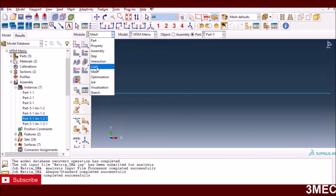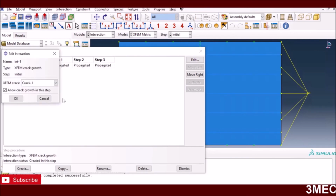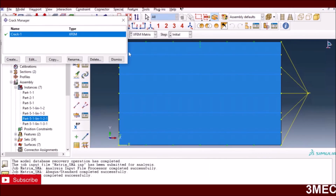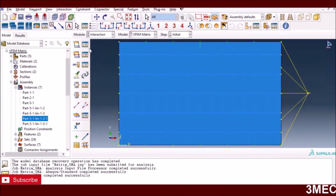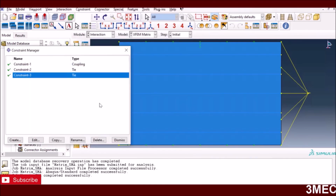All right, and yeah, interaction I didn't show you. So interaction I missed, for example. In this case I have an interaction which is the crack. If you go back to part 1, I showed you how to define this crack. You have to go to special, if you remember, and you see I have defined an XFEM crack. You have to select the geometry, and then you have to select the crack. Where is the crack? You have to pick this crack line, and the whole process is explained in part 1, so have a look at that. So this interaction is basically about this crack, which we have already discussed. We have the interaction type and property, and this is just involved in the crack part.